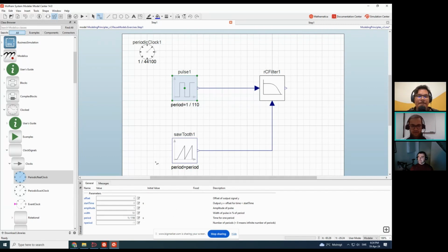Okay. So right, and then let's give a value to a sawtooth. And as you said, Leo, for the potentiometer, we don't want the resistance to go to zero, else it will lead to a short circuit of the RC circuit. So let's use an offset here of 0.001.